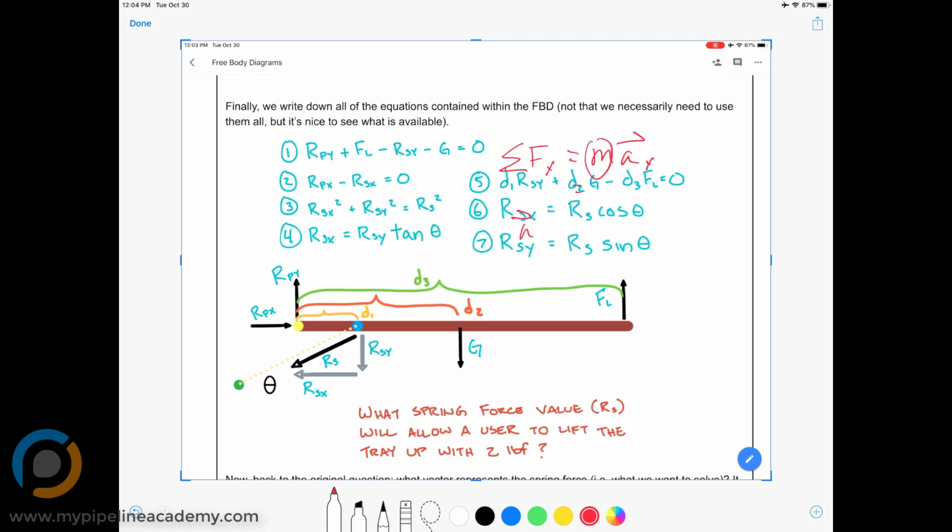We also do this one. Yeah, it's the same thing. We don't use that one, because we're assuming there is no acceleration, and we're just looking at forces, not the force equation, which is mass times acceleration. If there's no acceleration, we turn acceleration into a 0, and then the sum of F y divided by m, we multiply by m on both sides, and whatever this m is, it cancels out. So really, we end up with the sum of F y.